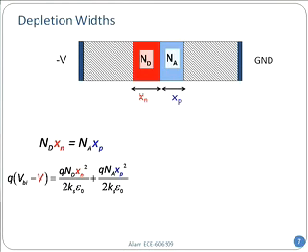Do you understand that? The current would simply flow because previously diffusion and drift were exactly balancing each other, right? Lots of electrons on one side, very few electrons on the other side. They want to go in one direction, and the electric field built up because of the depleted charge pushed it back. It's like having a river, lots of water, then a bank of the river, which is a potential barrier. So although you have lots of water in the river and no water in the dry part, of course by diffusion it would want to come, but the bank of the river is essentially preventing the water and keeping it confined.